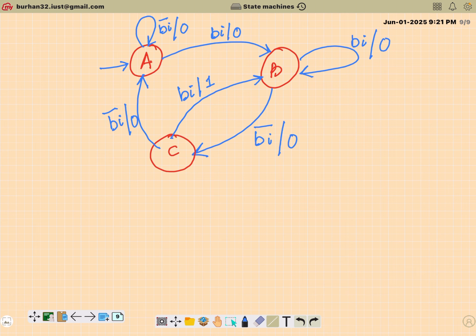And the coding strategy will be the same. You'll start with, as usual, library declaration, then you will define your ports in their entirety. In the architecture, you will first define a user-defined data type by whatever name you like. Typically, we use state. And that state will have only 3 values, A, B, and C. In the Moore machine, we had 4, A, B, C, and D. Then you will initiate a process for the implied clock. And you will initiate a second process wherein you will use the case statement.